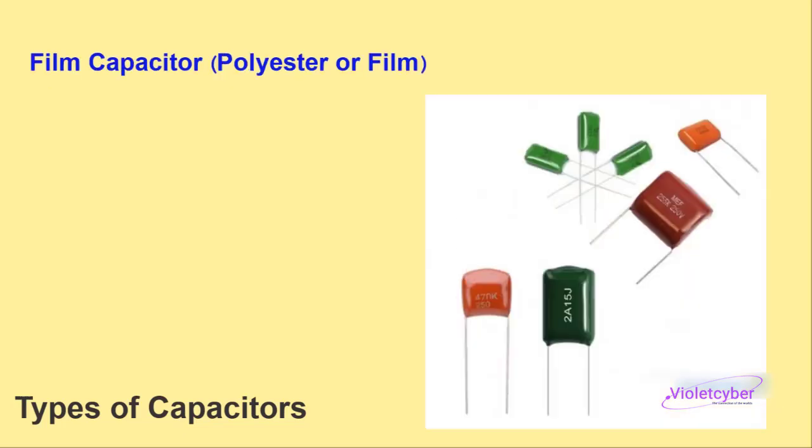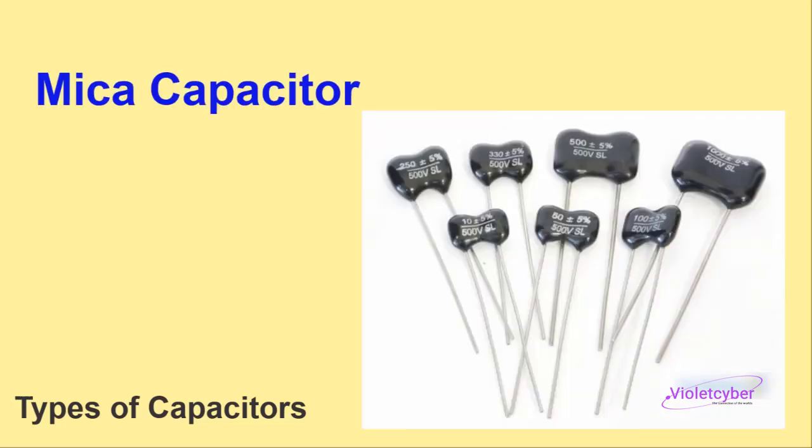Film capacitor, polyester or film: high capacitance and voltage, high stability and long lifespan. Applications: high power circuits. Mica capacitors: high thermal and frequency stability. Applications: precision circuits and high frequency circuits.